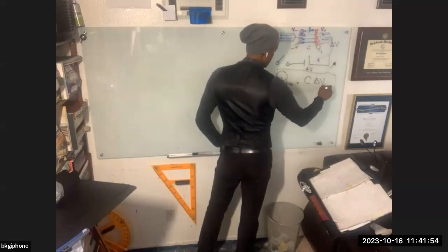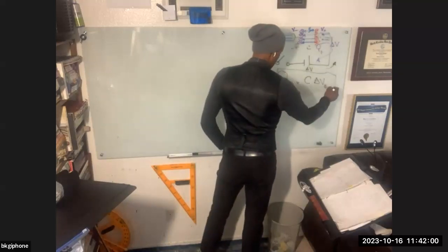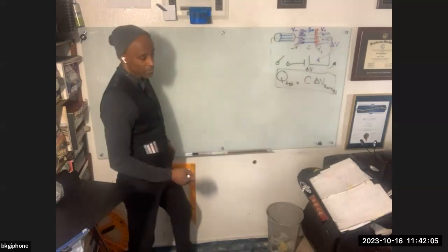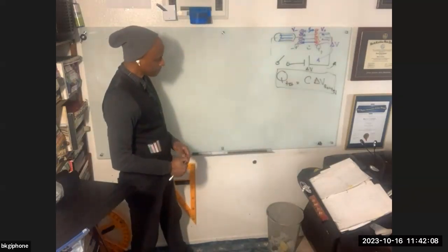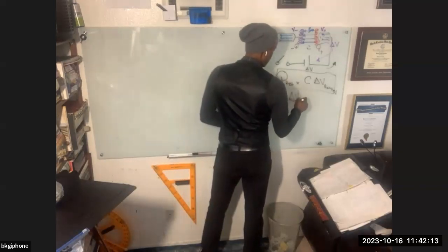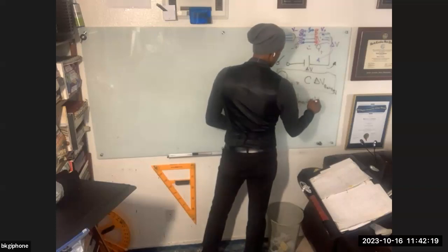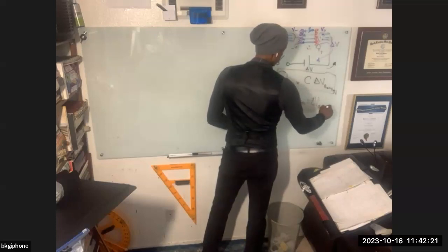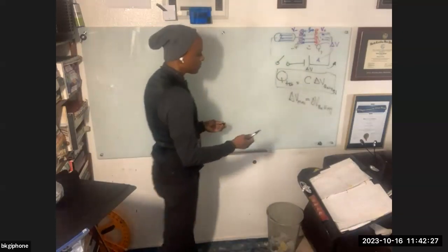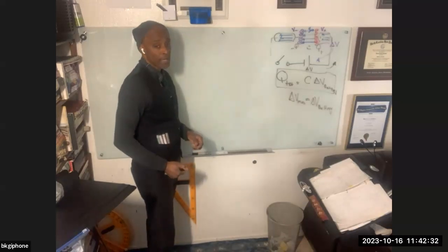So basically, you could say that the total charge on a capacitor is going to be equal to the voltage of the battery times the capacitance itself. It's always going to be that. The maximum charge on the capacitor is equal to that. Because the delta V max of the capacitor is going to be equal to the voltage of the battery when it's fully charged. Well, we're talking maximum here, so that's implied. So why is that?